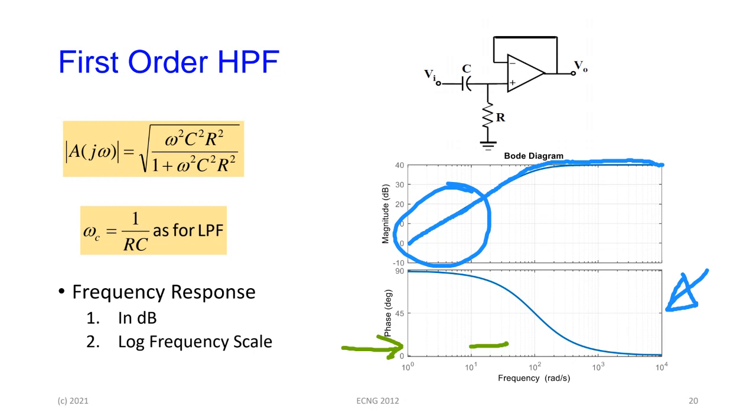This space is a decade. Exactly. So the slope here, you notice over the decade, it's going from 0 to 20. So in other words, the high pass filter response is plus 20 dB per decade, right? The low pass is minus 20 dB per decade. The high pass is plus 20 dB per decade. That is the effect of the 0 in the response. And we will see how that turns out, as I say, when we talk about both plots later on.